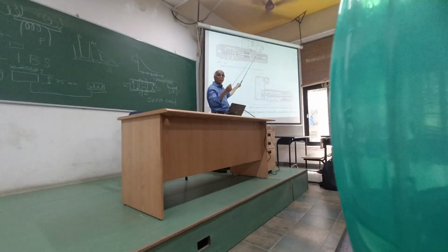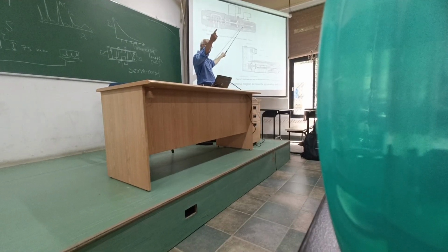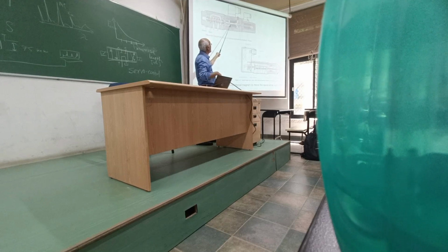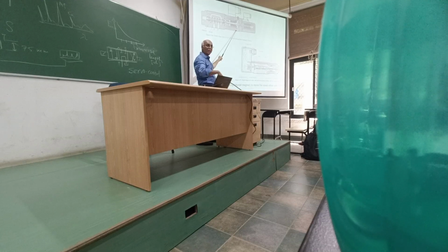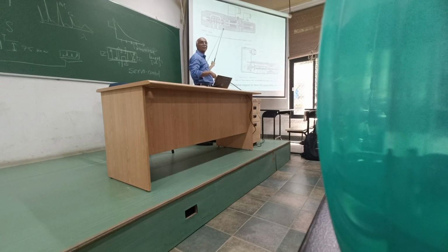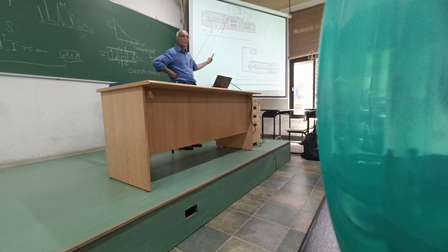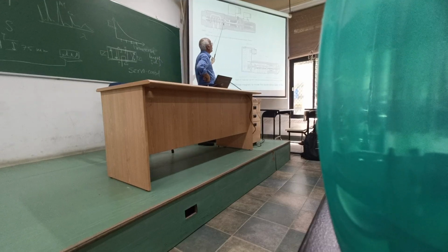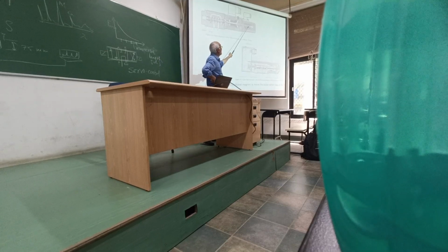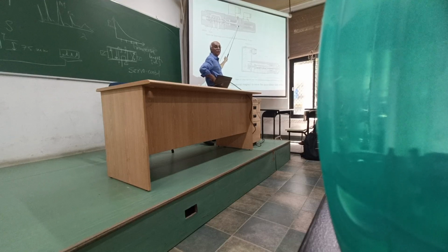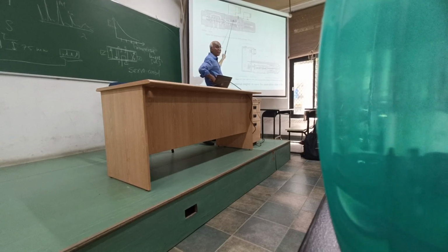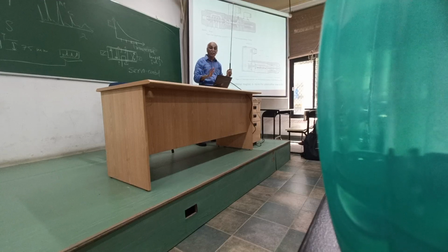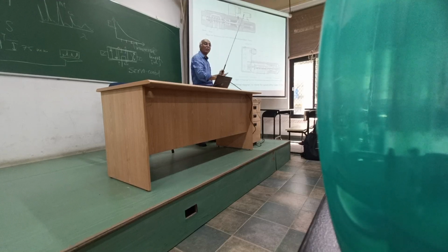That output is being fed to the controller, which provides the output to the solenoid valve and changes the current rating to position the spool. So the position transducer: let's say the spool moves, accordingly this position will change, and accordingly the current required for generating the same force to move it will change.